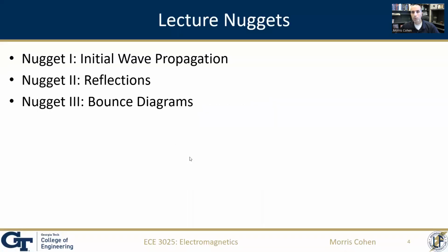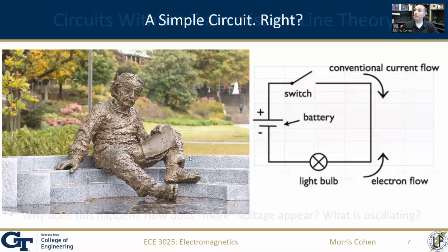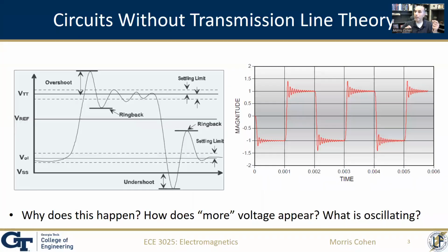At this point, you can hopefully see how this ringing can occur. Because if I have reflection coefficients on both ends that are correct in a certain way, we'll get to that later, then we're going to get this back and forth over and over again, right? Too big and too small, and too big and too small, and eventually it settles out because, again, those reflections are being multiplied by a number that is somewhere between -1 and 1, or has an absolute value that's less than 1.